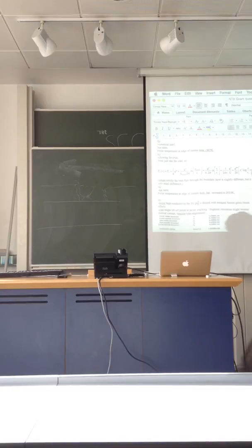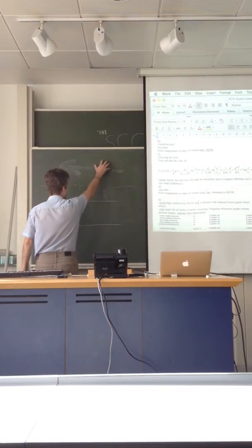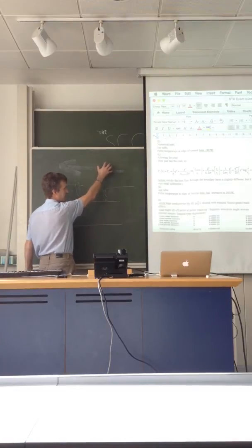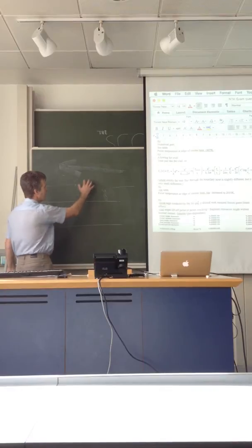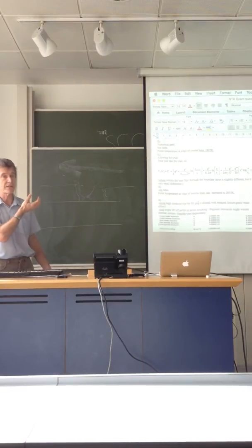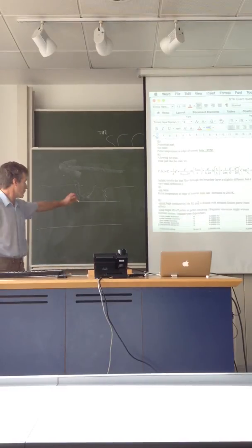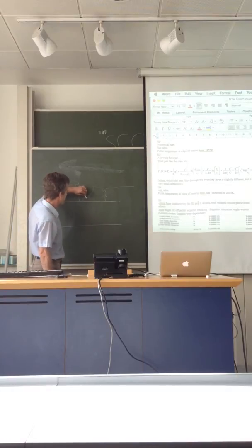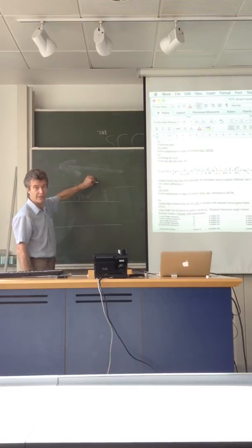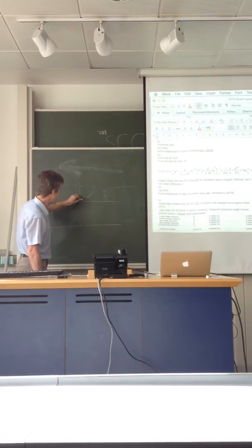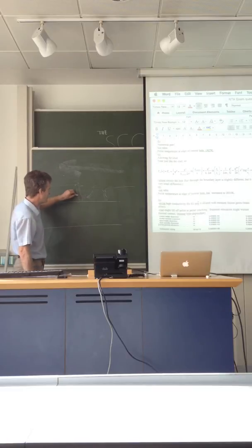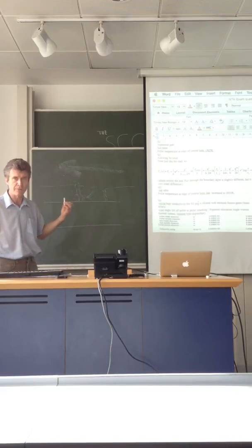So what you end up with is a build-up: whereas you have fairly low concentrations of nickel and iron and all the muck that's in there off the heat exchangers, it builds up to quite high concentrations in these regions, meaning 10 times or more the concentration out in the free stream. But it's got nowhere to go, so you build up high concentrations that form an equilibrium, because they start to diffuse backwards down that concentration gradient. But the water that's boiling down here is actually boiling in a very, very concentrated solution of whatever.